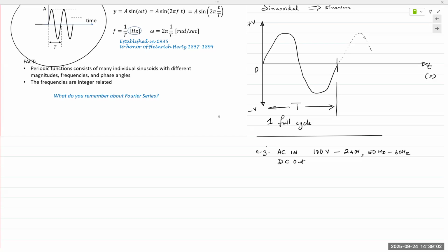So DC out, let's just say a typical cell phone or tablet charger would be 5 volts. Let's keep it small. The first ones were actually only 1 amp, and then came along tablets. They were like 2 amps. So a 10-watt charger: 5 times 2, 10 watts.